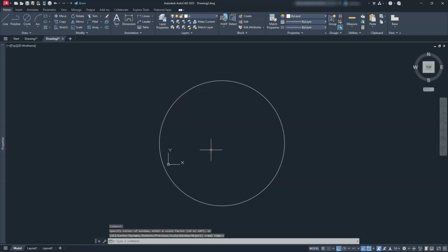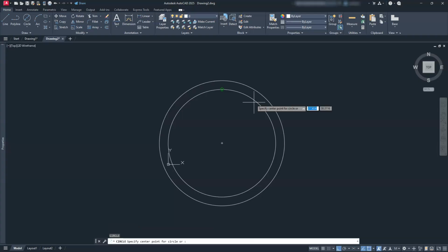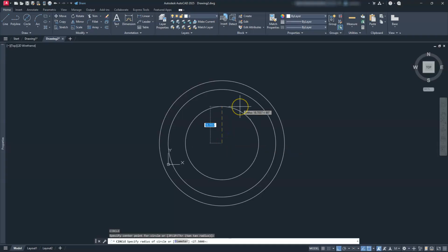And then what I would do is just constantly create these other circles. So you can do the same thing by coming up here to the top, come back to here, and then we can make our next circle, which is at 55. We can go a little bit faster than that just by hitting C enter. Right, come down here to the center of this. Once I click that, I'm going to type in D enter. Right, we did our 55.